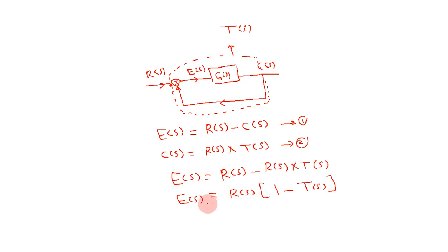In order to find the steady state error, which we call e_ss, the steady state error is usually the limit when time goes to infinity for the value of error. So you have the error function, which is the Laplace inverse of E(s), it is e(t). We said last time, if we want to find the Laplace inverse, the capital letter becomes small and the s becomes t. We don't know the values, we are just talking about the symbols here. So the steady state error, the formula says, equals the limit as time goes to infinity.